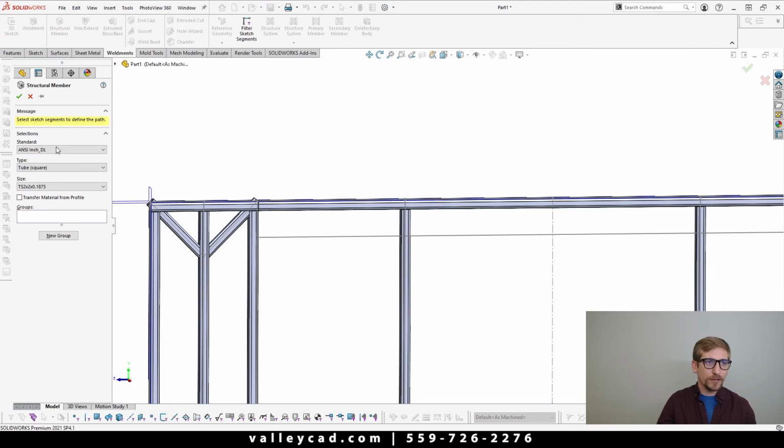We'll do structural member again. And in this scenario, what we need to do is create a bar that comes across here. Now, I don't have a bar profile currently. As we look at here, I got a wood profile, unistrut, standard, ISO, 80/20 extrusion. But I actually, oh, there it is. There's my rectangular bar. And we'll make it so it's a 1 by 4.